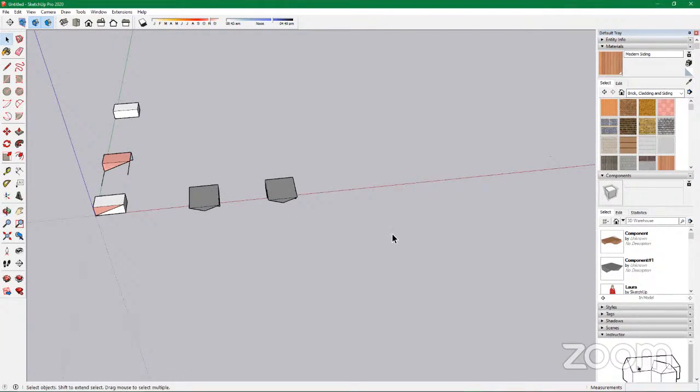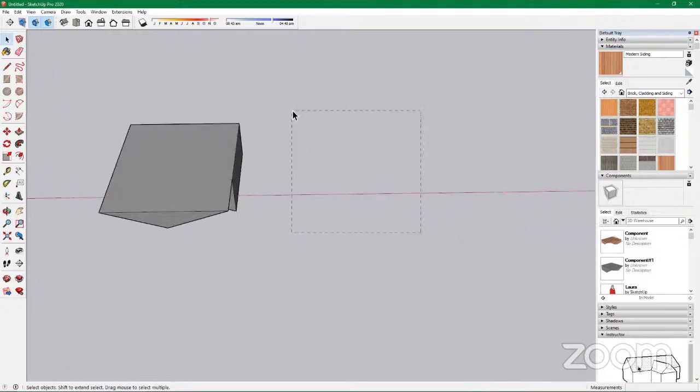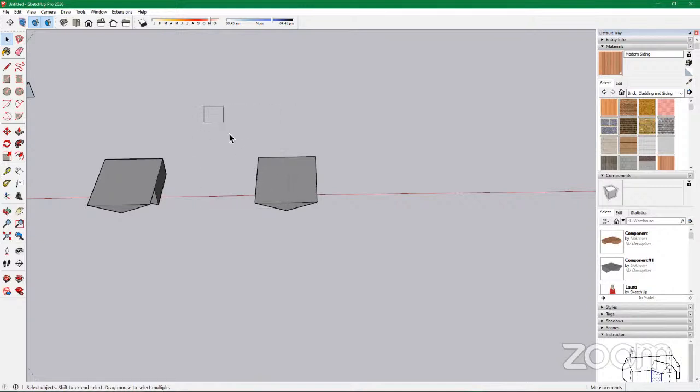All right, for AutoCAD, I told you about the blue and the green selection window. It's also applicable here. So you know the green selection window is the selection window having this detail. The lines are dotted. Yes, we have these dotted lines for the green selection window. By the blue selection window, we have a complete rectangle. Now that's for AutoCAD. For SketchUp, both of them are gray. They are all black, like you would call them. But you know the difference. If it has these dotted lines, it means that anything it touches will be selected, like so. But if it has this other rectangular line that is not dotted, you have to cover it fully for it to be selected, because if you do like this, it will not be selected. You have to cover it fully for it to be selected, like so. Meanwhile, we have this one. This one does not need to cover it fully and to select all. Do you understand that? That's for selection, actually.